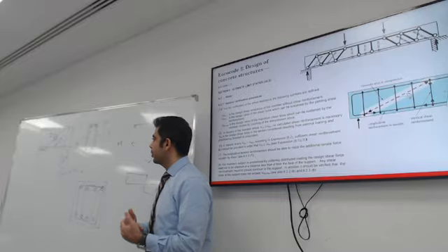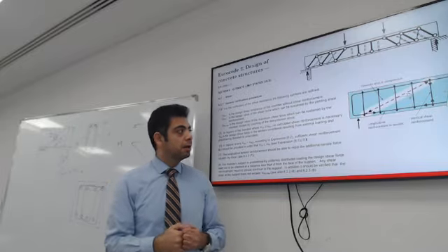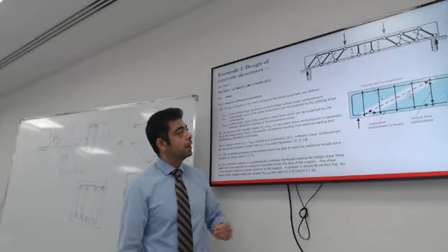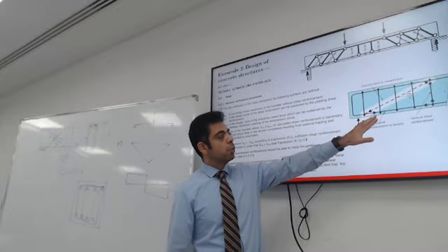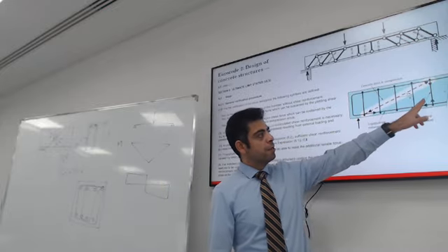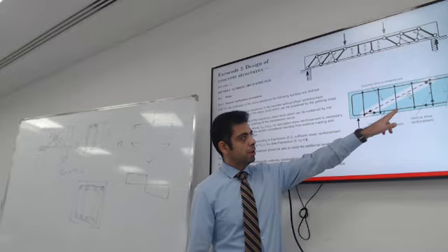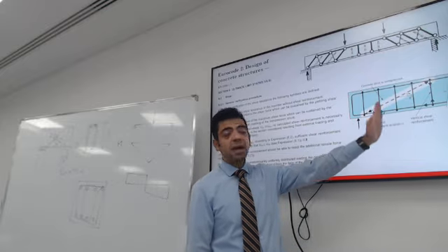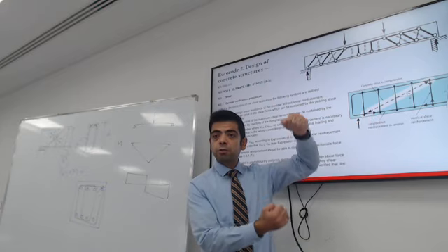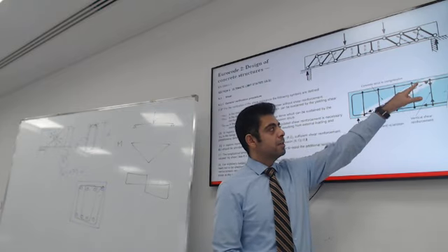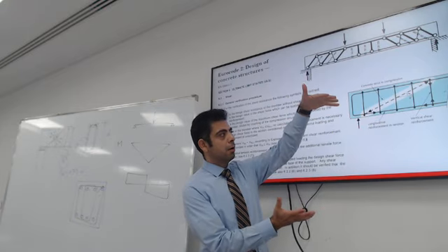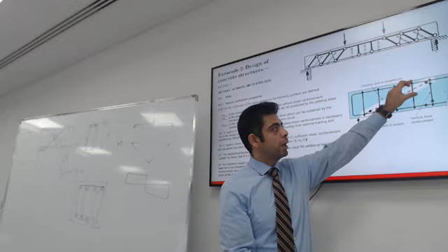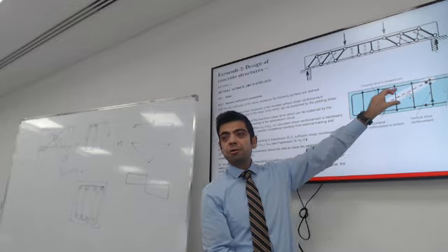There is another interesting guidance from the code, which is that the function of the stirrups is to resist the tension due to shear, and the horizontal and vertical components of shear will work their way into a compression strut.